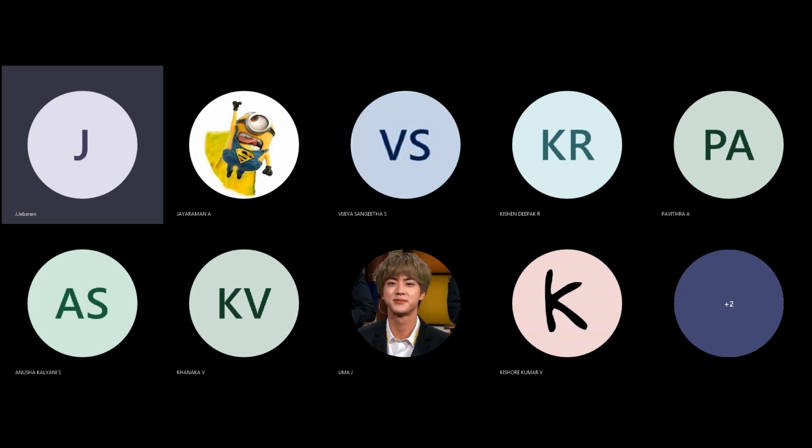Then the front also cools the melt as it is pushed down the mold cavity by water pressure. So the water pressure is somewhat high when compared with gas pressure. Normally, in the case of gas assisted injection molding, the pressure range is 300 to 2500 psi.